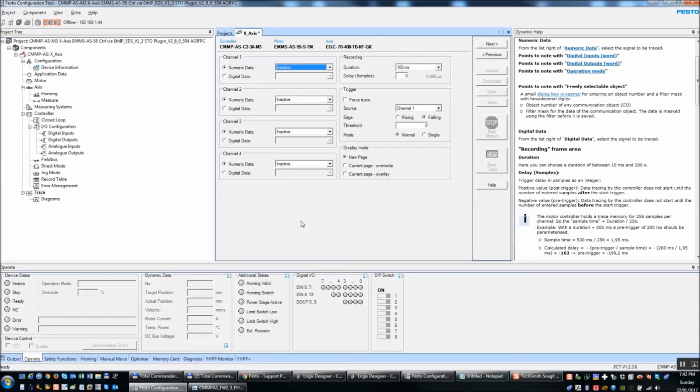It's now stored on the volatile memory. So if you were to cycle power to the controller, which you normally have to do in order to modify communication settings and whatnot, and so the cycle of power happens, and now the controller is back to where it was before you download because you didn't do a store. So brings us to the next one, the store.